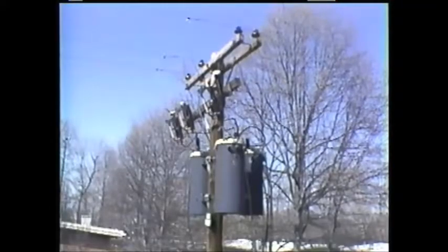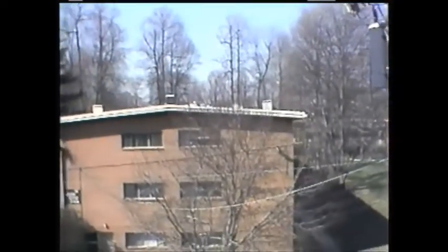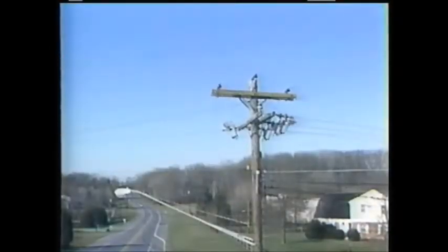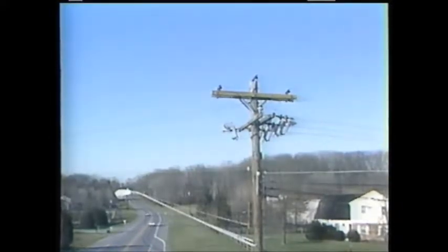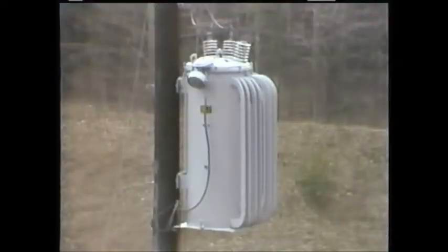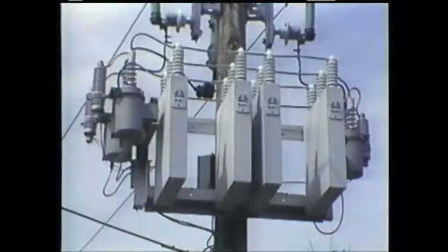In the last part of this program, you learned that distribution transformers are used to change primary distribution voltage to secondary voltage, which a customer can use. The value of voltage carried by a distribution line can be affected by changes in customer load demand and electrical characteristics that cause power losses. In order to compensate for these losses, voltage regulators and capacitors are used.